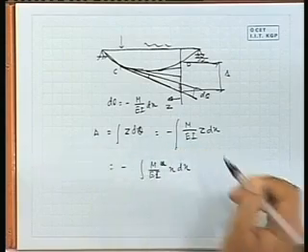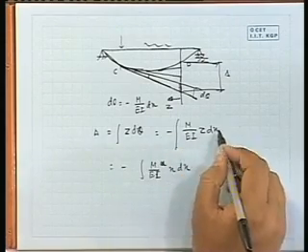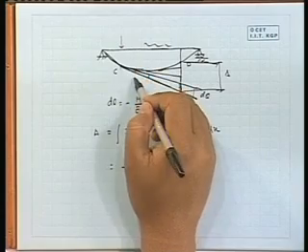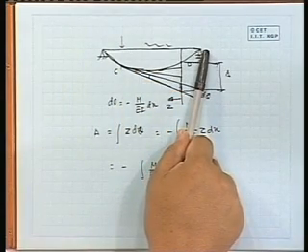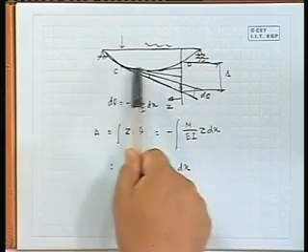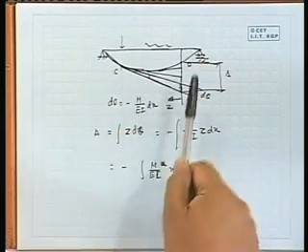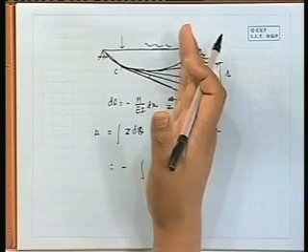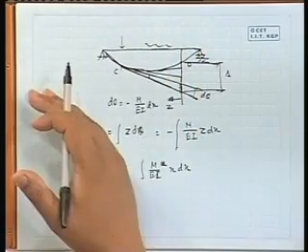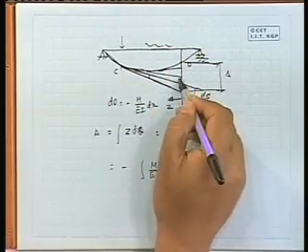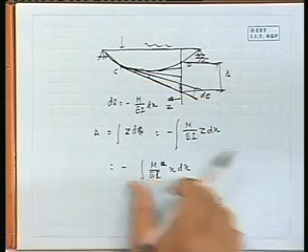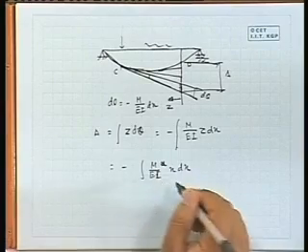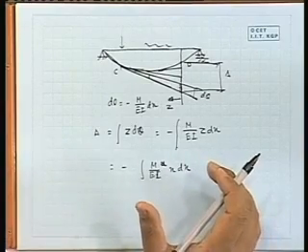Now what is d theta? D theta is M by EI into dx. So this dx part is this one. Okay. Now dx, we are measuring x from here, right, and dx is this one. So if we shift our origin, say dx we can take as a dz, okay, no problem, because from here it is z and this part is dz. So dz into, so entire quantity we can write as dz or x dx, in any form we can write. Okay. So it will be more or less same thing.